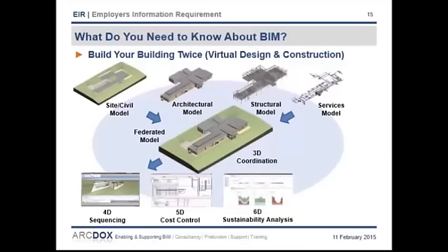Adding the 6D, or structural and energy performance data, to the model will facilitate the carrying out of sophisticated analysis of the building to help predict the future performance and running costs, and will also allow the team to test multiple iterations and come up with optimized solutions that will reduce construction and operation costs. And lastly, the gathering of vital asset information of all the components of your building in this digital model to transfer this to facilities management software, or 7D, will also save enormous amounts of time and cost at handover.